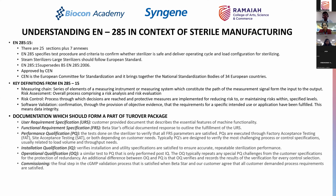Okay. Key definitions: measuring chain, series of elements of measuring instruments or measuring systems which constitute the path of measurement signal from the input to the output. From the input to the output, sorry, there's a spelling mistake there. So measuring chain is nothing but what are the devices and systems that you're using to measure the various parameters which are used in the autoclaving process, and how that signal is getting transferred. How are you measuring it, and how are you seeing the output of that on the control system?